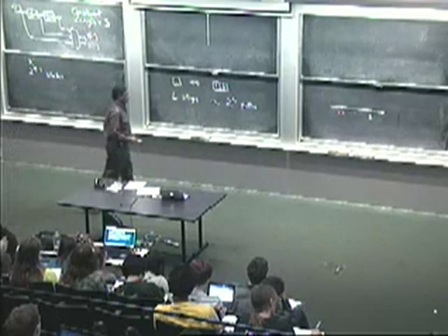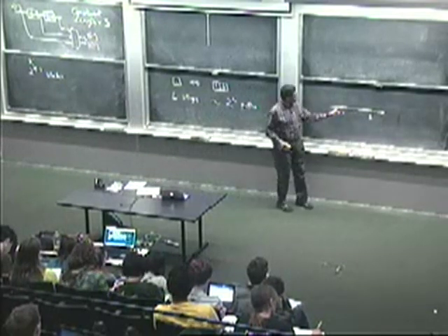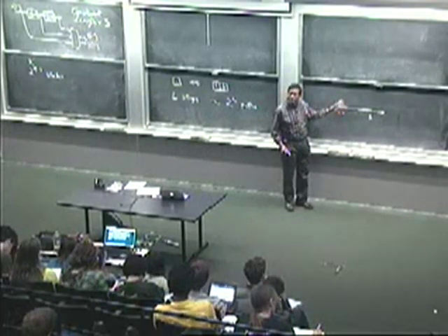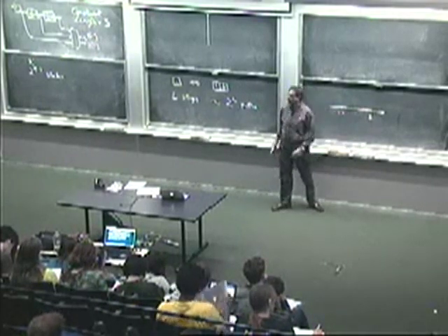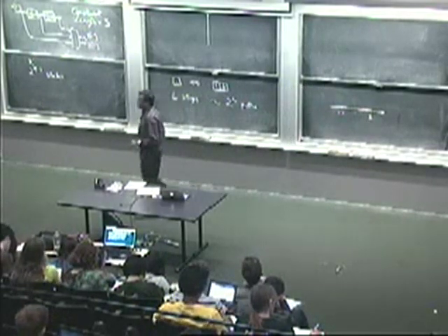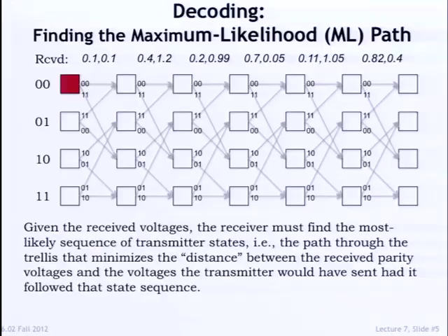And if the noise is really bad, then, of course, what started off as a 0 here with the noise added to it, by the time you sample it, might fall in a region where you call it a 1. All right? So there is an intermediate step, and very often you have access to that. And then you've got to figure out how to do your decoding.